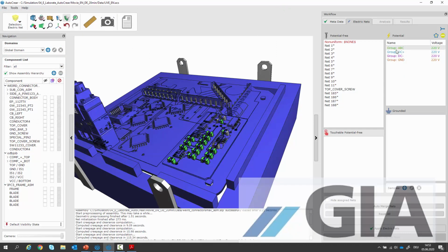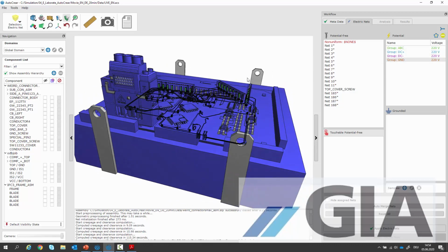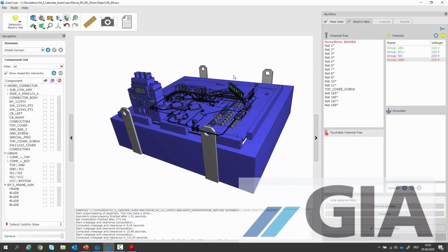I'm creating some groups here and everything is assigned in this group, because quite often I have to make sure that my distances between the groups have a certain distance, and therefore this is a very big help. Okay, of course now because I loaded them, I have to define my networks again, but it's no problem. I will apply these networks, then I will analyze this, but the analysis on my old laptop takes about 40 minutes, therefore I'm loading a session.